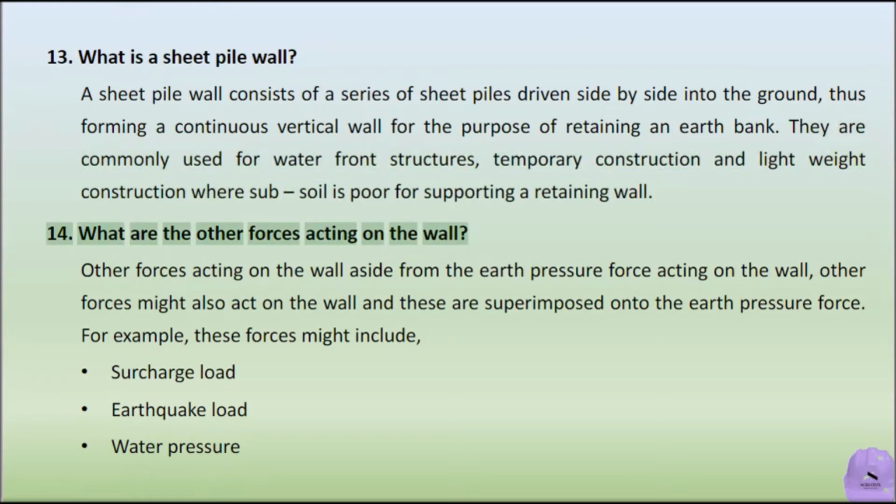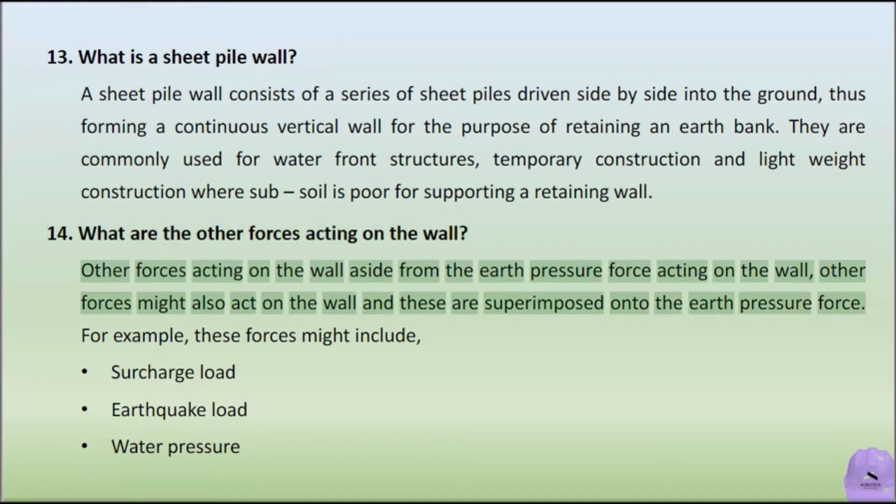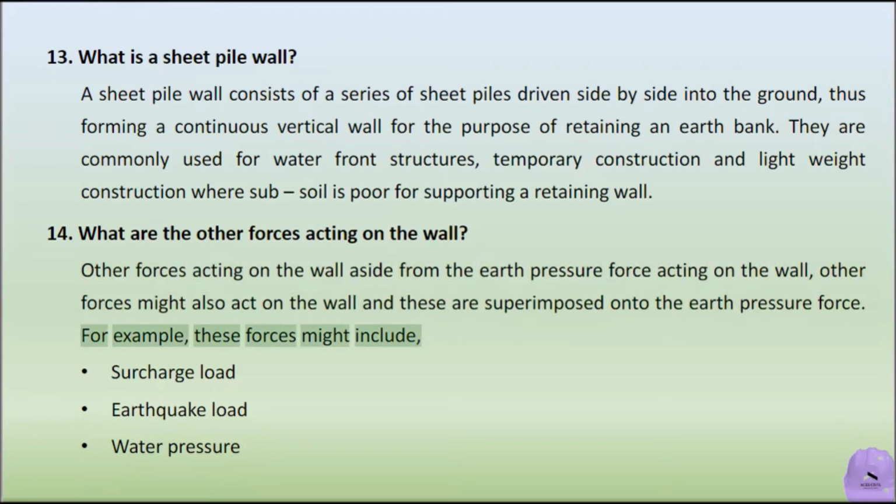What are the other forces acting on the wall? Aside from the earth pressure force acting on the wall, other forces might also act on the wall, and these are superimposed onto the earth pressure force. For example, these forces might include surcharge load, earthquake load, water pressure.